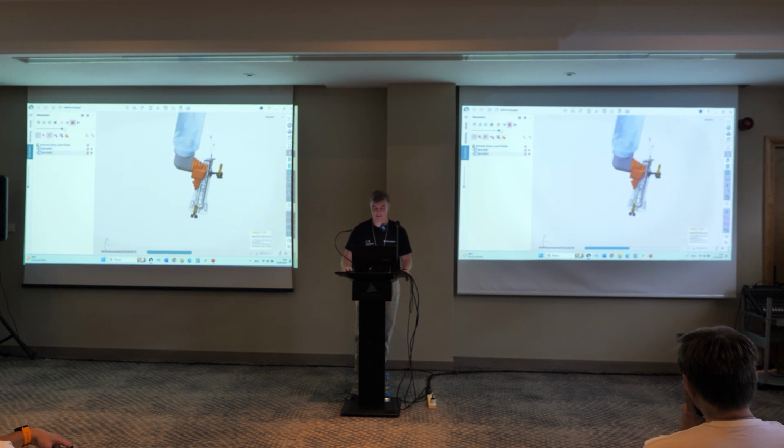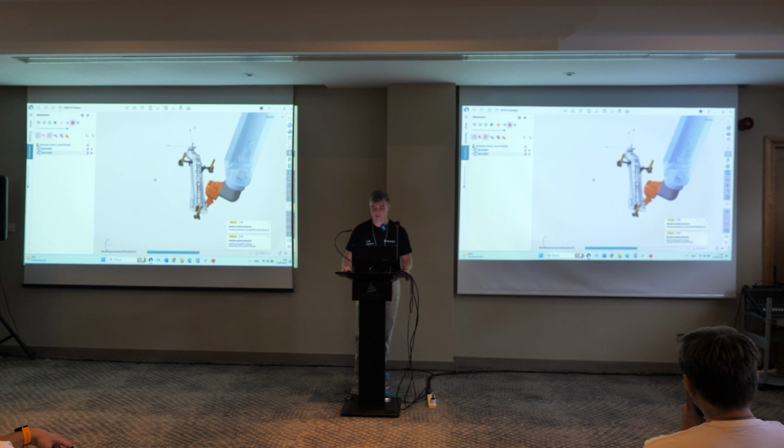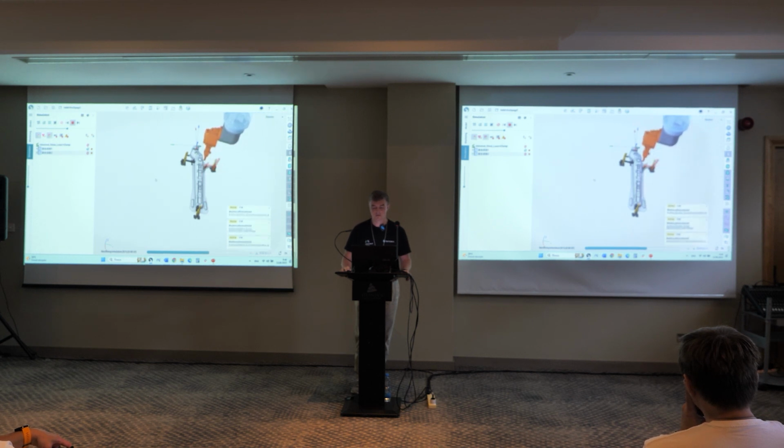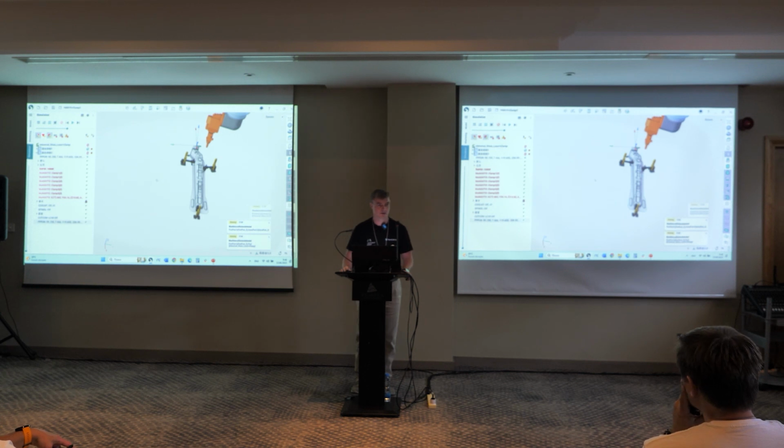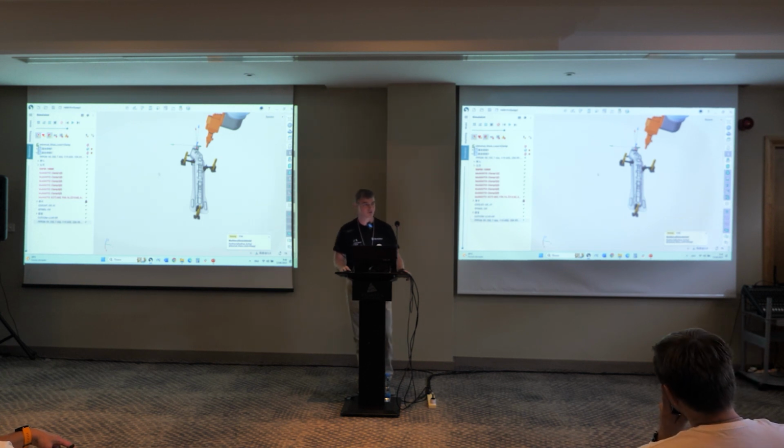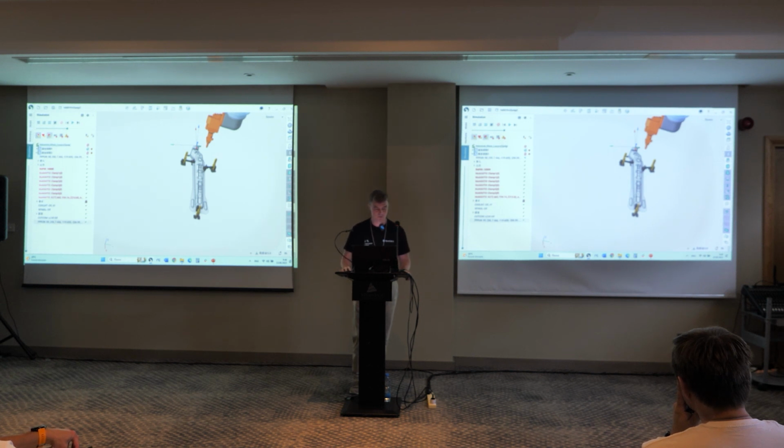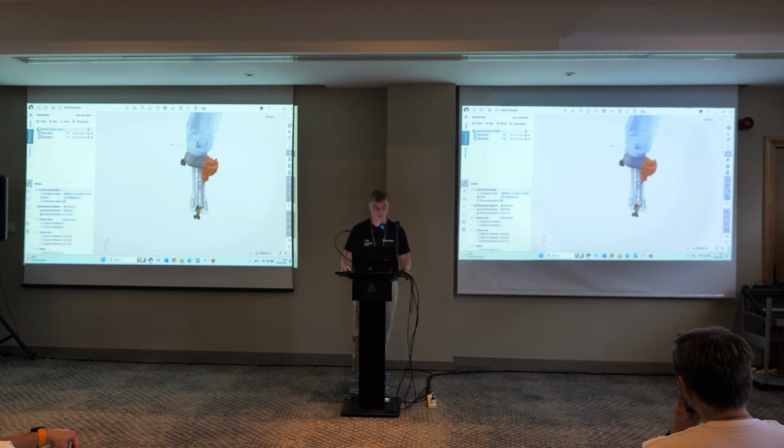Next, clamp open, close, open, close. So how was it done? Honestly, SprutCAM technology did nothing to make it. It was totally made by the Chinese dealer. And how was it done? First of all, in the machine schema, in lines, we have the axis, machine state parameters, clamp 1, and these parameters are enabled here. Clamp 1, clamp 2, clamp 3. It is described in the machine schema.